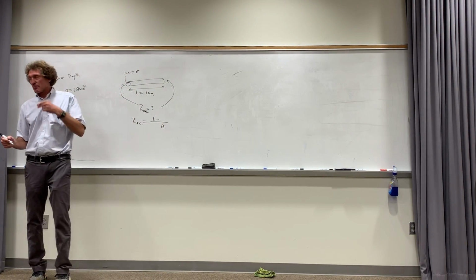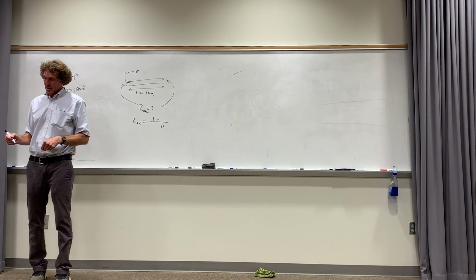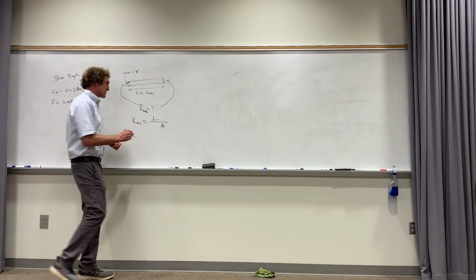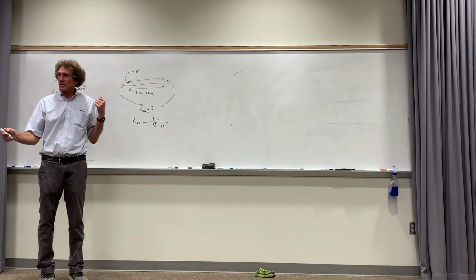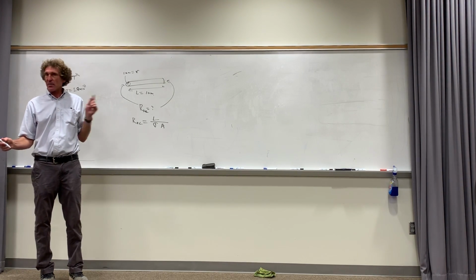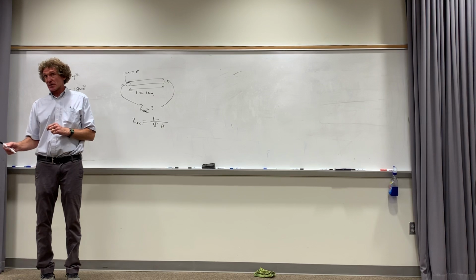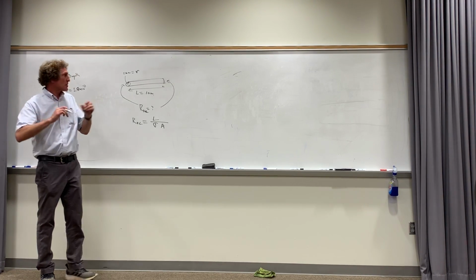And is it inversely proportional to conductivity? Just think about it. Inverse, right? And that's the general formula for resistance for anything with constant cross-section between the ends. Now let's do DC. In our case, area is what? It's really a circular plate, right? That's where all the current's flowing in.